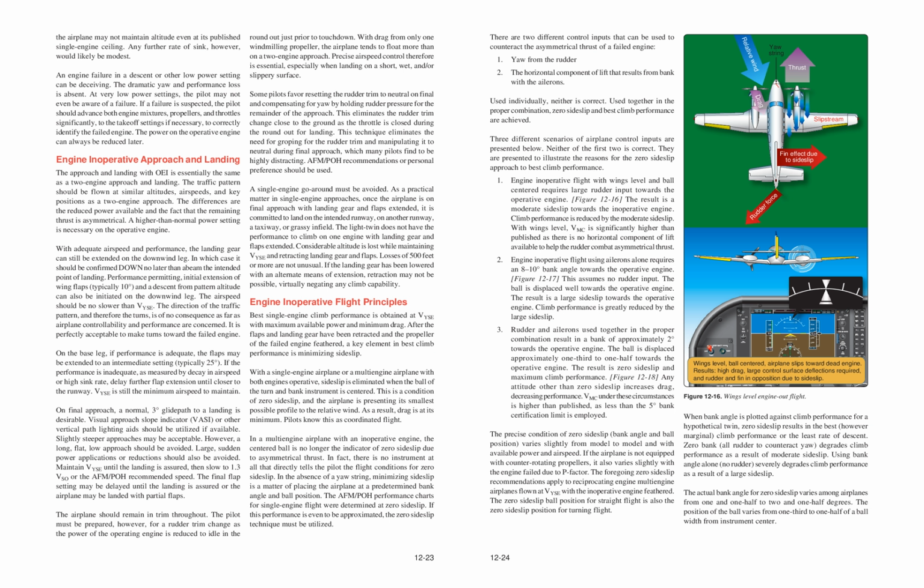The AFM/POH performance charts for single-engine flight were determined at zero side slip. If this performance is even to be approximated, the zero side slip technique must be utilized.